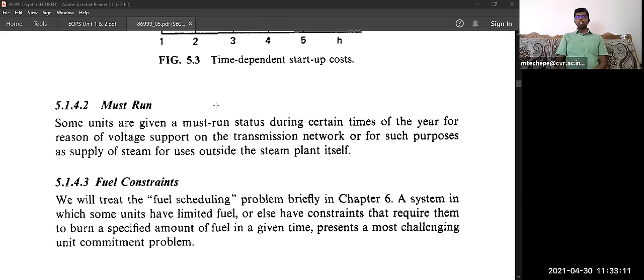In that scenario, we can go for operation of a very small generating unit. Instead of turning on thermal generating units, we can generate from hydro units. Why? Because thermal generators start from a minimum of 500 megawatt, 1000 megawatt, 1500, 2000, like that. There will not be 100 megawatt units like that. Maybe there, but only for reserve purpose, not in normal operation.